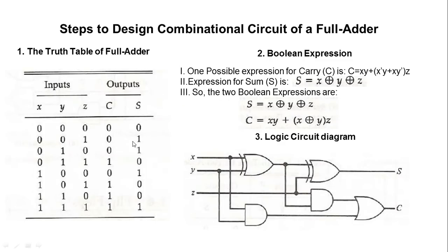So let's understand the truth table in detail. This truth table works the same way as I was explaining. XY can be 0 0, and for both 0s, the input carry can be either 0 or 1. We are not sure; it could be any case. Same for 0 1, because the carry can be either 0 or 1. For 1 0, it could be 0 or 1 as an input carry. Same is the case for the last double ones. Sometimes I can get 0 as a carry, and in some cases I might get 1 as a carry from the previous output value.